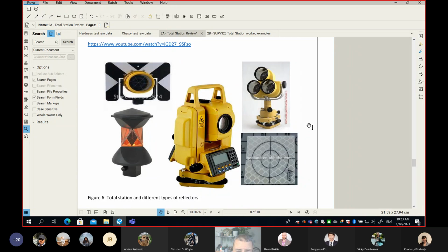And as I said, this is very convenient to use in conjunction with a robotic total station. Because if you remember the video that I showed you last class, it doesn't matter what the orientation of my prism is. That's why my surveyor wouldn't spend any time or effort to rotate it and make sure that it faces your total station, because he has so many other jobs to do.